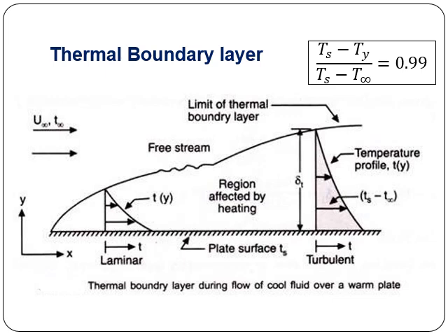Wherever I get the temperature difference between the surface temperature and the fluid temperature equal to 99% of the maximum temperature difference, that is Ts minus T infinity, so if I consider Ts minus T infinity as 100, wherever I get 99 degrees, I'll mark those points at different values of x, and if I join them, I'll get a boundary layer which is called the thermal boundary layer.